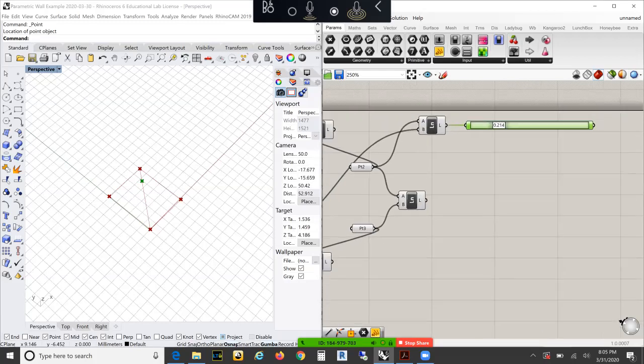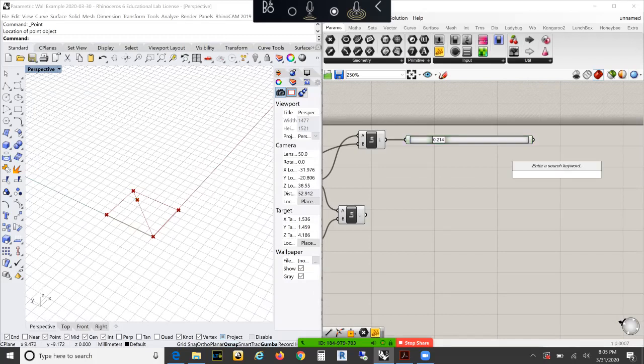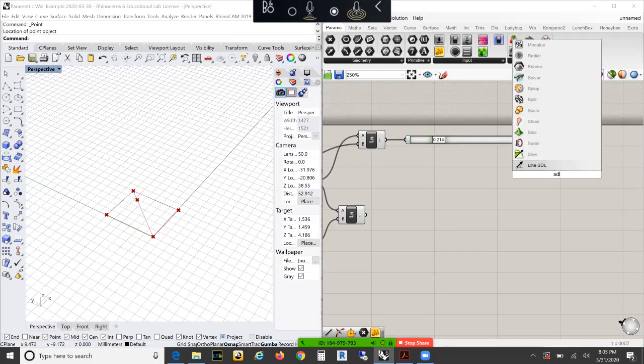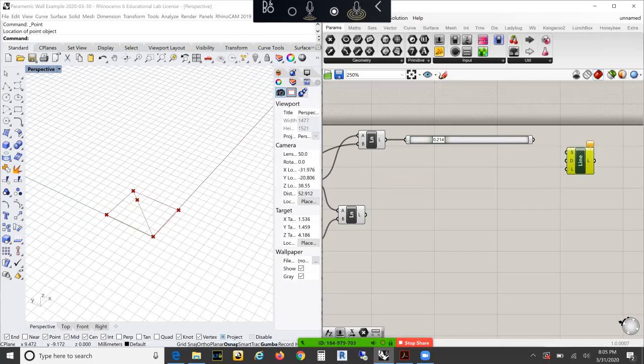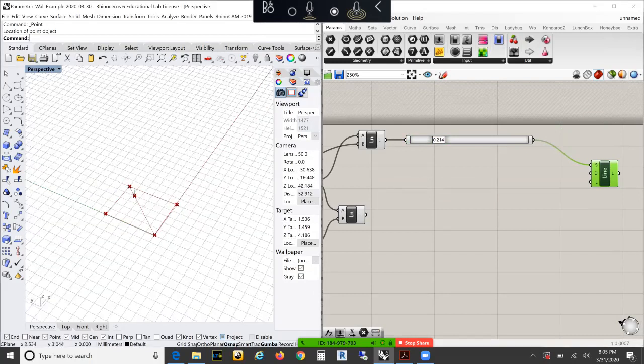But we're going to add something three-dimensional to this. So we're going to use an SDL line. Our starting point will be here, and our direction. Now, in most of the cases we were working with, the direction would be Z. In fact, right now the default is Z. But in this case, we're not really sure of the direction of this module.